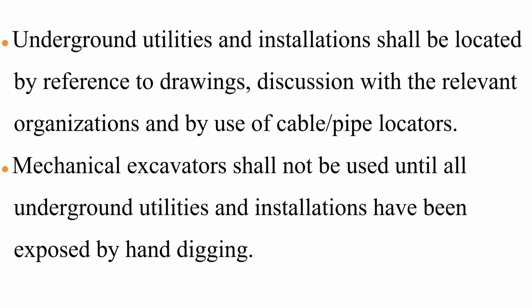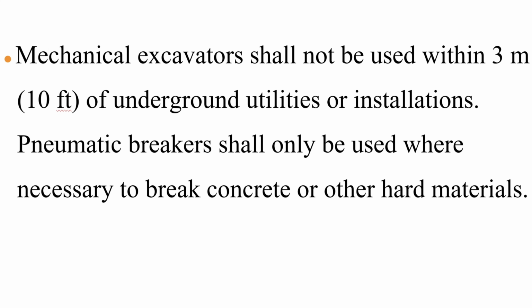Mechanical excavators shall not be used until all underground utilities and installations have been exposed by hand digging. Mechanical excavators shall not be used within 3 meters (10 feet) of underground utilities or installations. Pneumatic breakers shall only be used where necessary to break concrete or other hard materials.